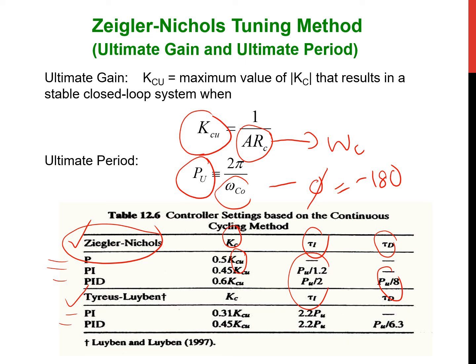So that is the chapter 4 topic, where you need to consider the frequency response: how the transfer function is converted into the frequency response for amplitude ratio and phase angle. Once you get the expressions for phase angle and amplitude ratio, you plot the Bode diagram. From the Bode diagram, you assess the Bode stability criterion, stable or not, or you can use the gain and phase margin.